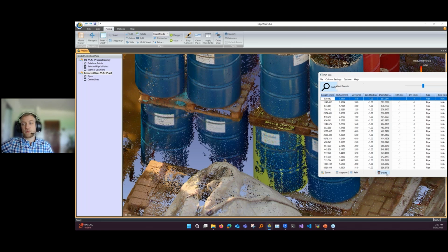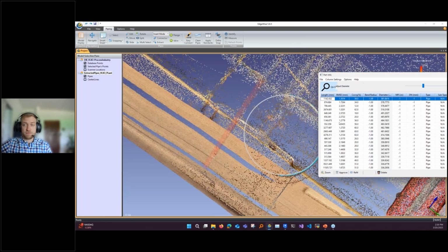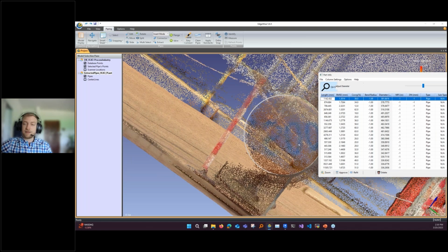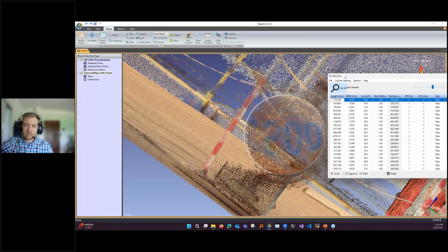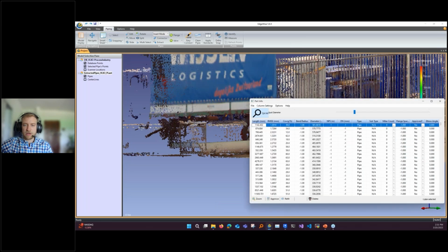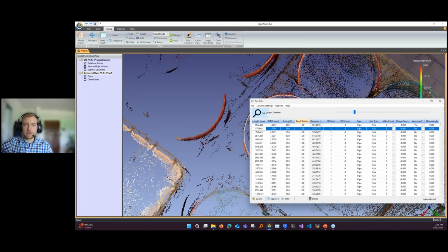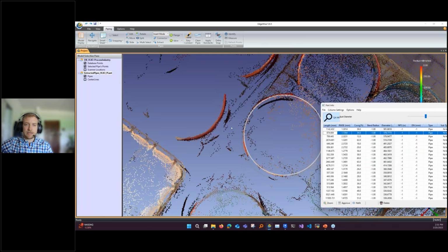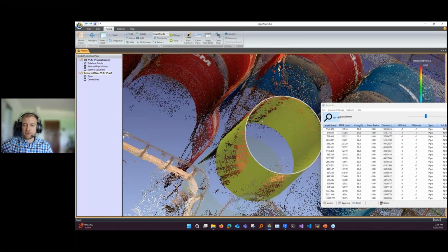This applies across the board for diameters too, right? If you only need to model piping that is a certain size and up or down, just delete everything outside of that scope. That's your first step, basically. And so that one looks good and we can approve it. There is an approve function and you can keep track of what you've done and work your way through the model that way. But that is, again, a different option for the different models.